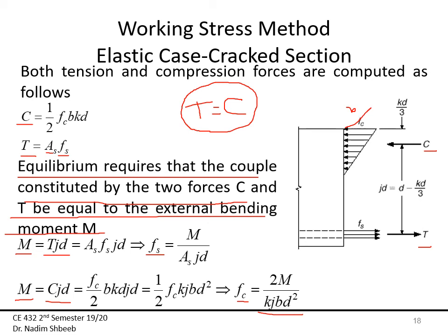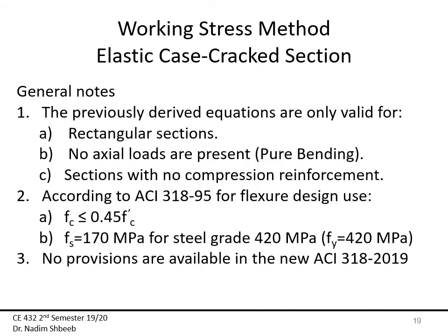So now, having derived the stresses in the steel and concrete, I'm going to have some general notes about the working stress method. The previously derived equations that we have given so far are only valid for rectangular cross-sections, which means they are not valid for circular cross-sections.